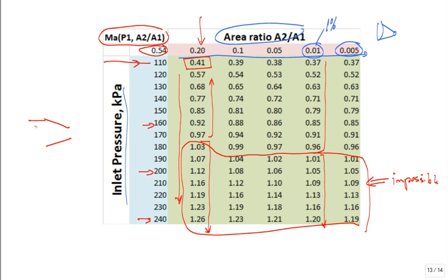But what will happen is if you go out into the lab and you build an experiment where you're able to control that back pressure right here, or the supply pressure, let me call it the supply pressure, and then you have it open up into this chamber here. As you boost the supply pressure, it gets choked flow. It gets Mach 1. And you can't go any faster unless you do something different with the geometry.